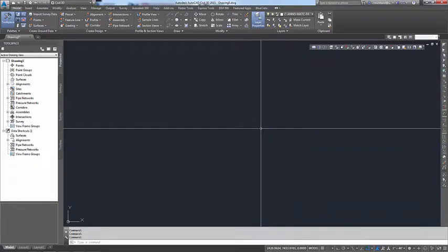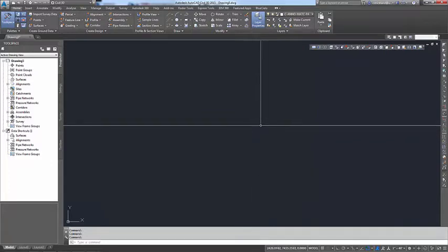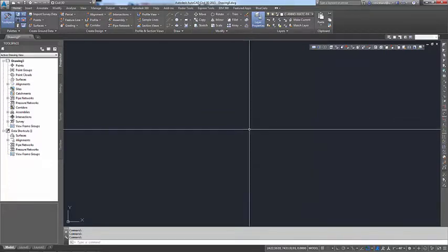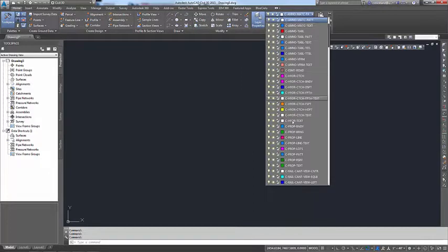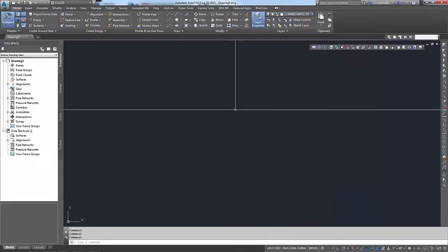Templates in Civil 3D are a requirement in my opinion. All of the styles that we will need have been created in some part and ready for us to use. This template, the Imperial NCS, starts off with dozens of layers created for our use. We can check up here, see what kind of layers we got going on. As you can see, we got a bunch already. These layers are contained in many styles.